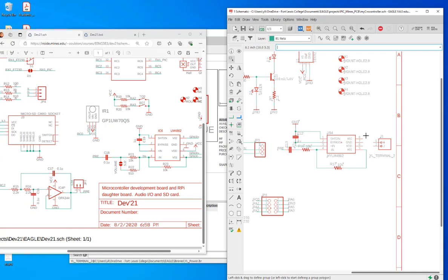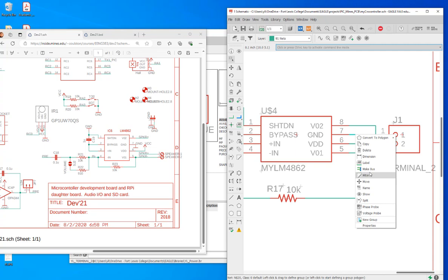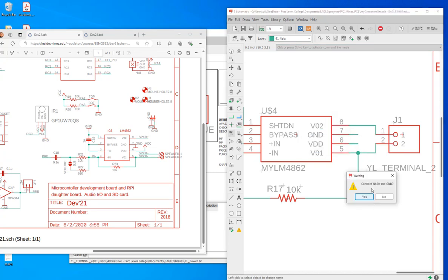Okay, and then this is speaker plus. See? The speaker plus is connected to the top, and then I got a ground pin in the middle. You can actually name it as ground. And here VDD, this is also shorted to here. So for these 2 pins, if you want to connect it to ground and VCC, so just do this. Okay, and VCC.